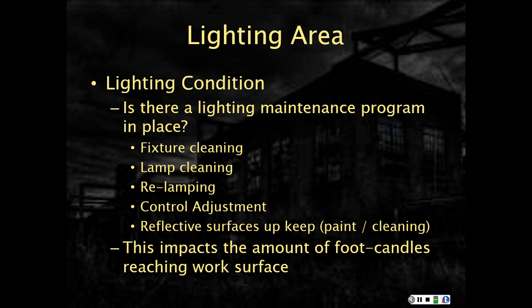Now, this impacts the amount of foot candles that reaches the work surface. That's the actual quantity of light reaching the work surface, which is the area where we're conducting whatever the business of the space is. That's the area that's regulated by code, industry standards, or whatever, in terms of how much light is actually reaching what we're trying to accomplish in that particular space.